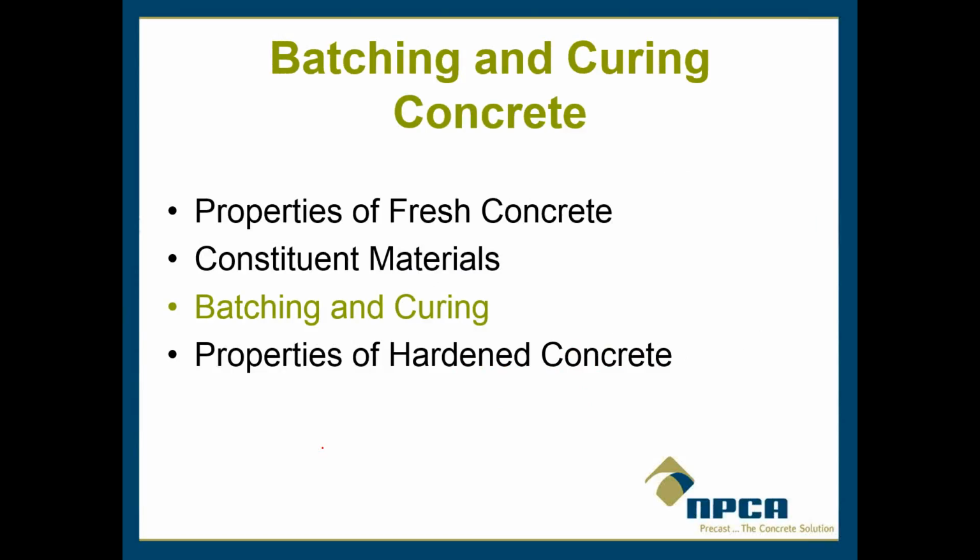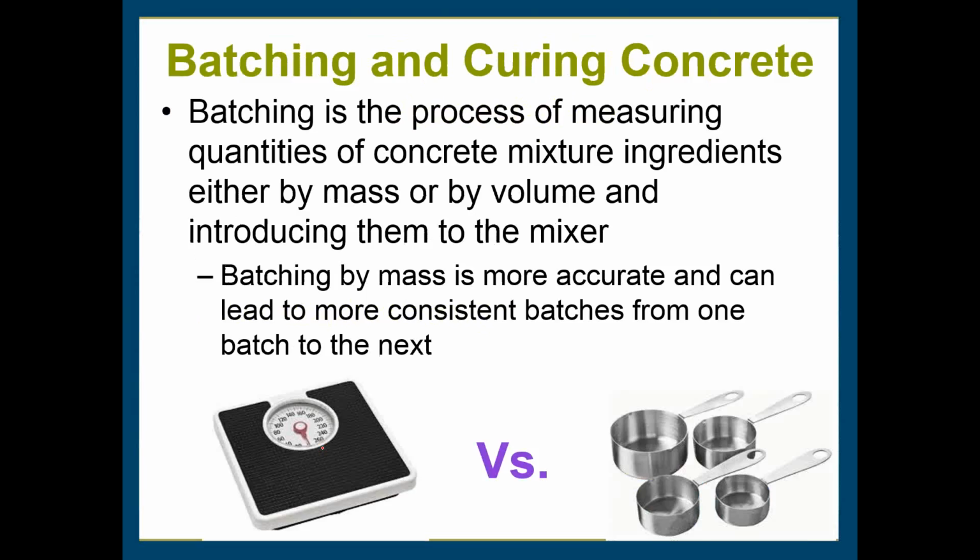Okay, on to batching and curing. Very, very important. So first off, does anybody here batch by volume or by weight? Can you let me know? Okay, so everybody has said by weight, and that's excellent because, not that there's anything wrong with batching by volume, but batching by weight is more accurate.